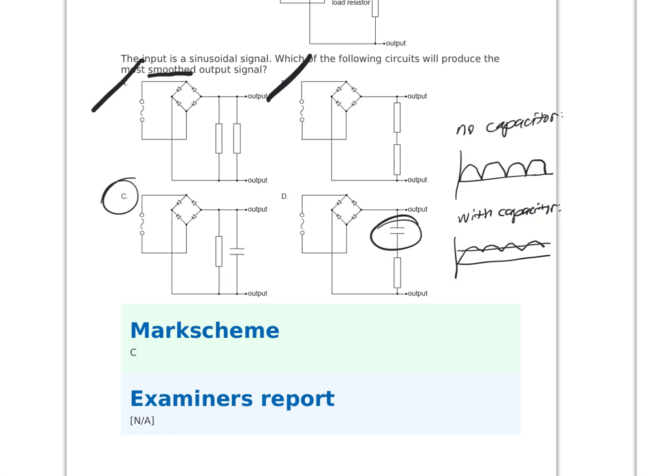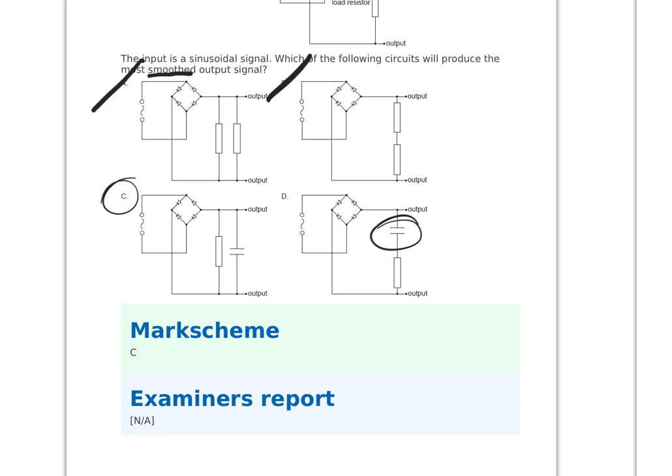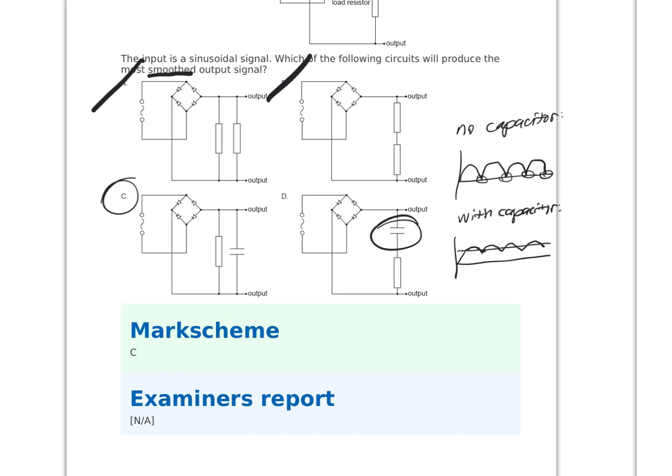It's kind of storing potential in it. So while the voltage dips to zero as the AC power source cycles without the capacitor, when you have the capacitor, that capacitor stores the voltage periodically, and so it does dip, but it doesn't get down to zero.